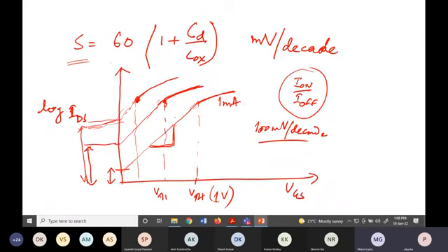So nowadays we have multiple threshold voltage MOSFETs in the same CMOS process, so that for the important MOSFETs where you need faster operation, you can go for low threshold voltage and sacrifice with a large off current. But for the MOSFETs where you don't need very high speed operation, you sacrifice the current, because VGS minus VTH will be lower, but you will be able to save the leakage current IOFF for those. So this is all I have to say.